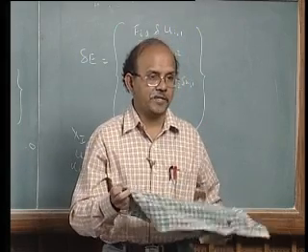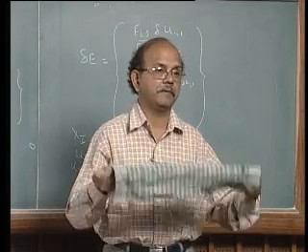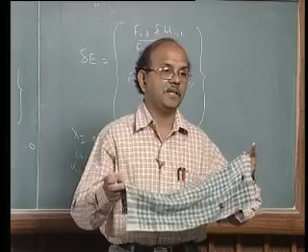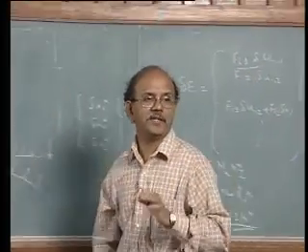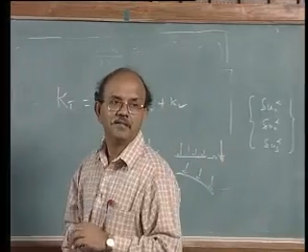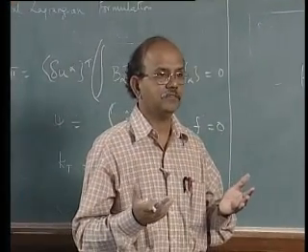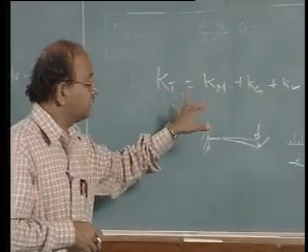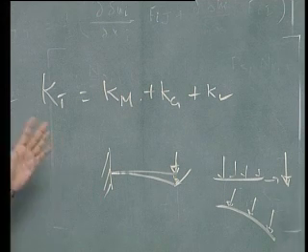The deformations in the other directions had, in fact, enhanced the stiffness of this cloth in a perpendicular direction. So that's why you cannot make a general statement that deformations reduce stiffness. Is this clear? Okay. So these are the three terms that are involved, and they are called Km, Kg,